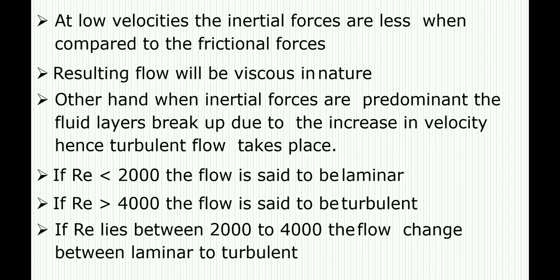So, if the Reynolds number is less than 2000, the flow is said to be laminar. If the Reynolds number is greater than 4000, the flow is said to be turbulent. If the Reynolds number lies between 2000 and 4000, the flow changes between laminar and turbulent. It depends on the conditions.